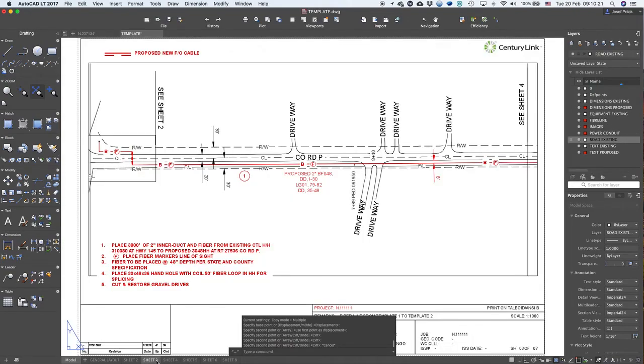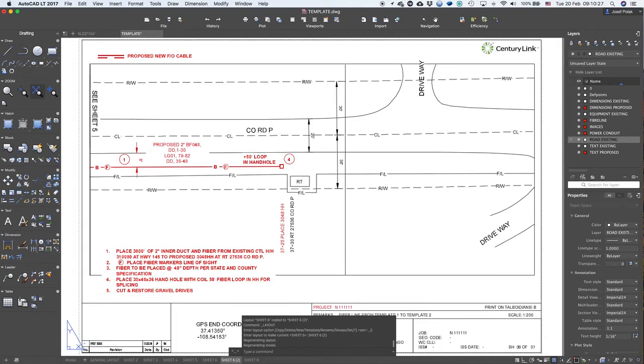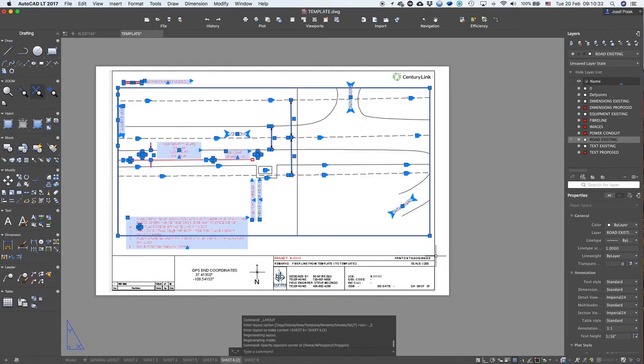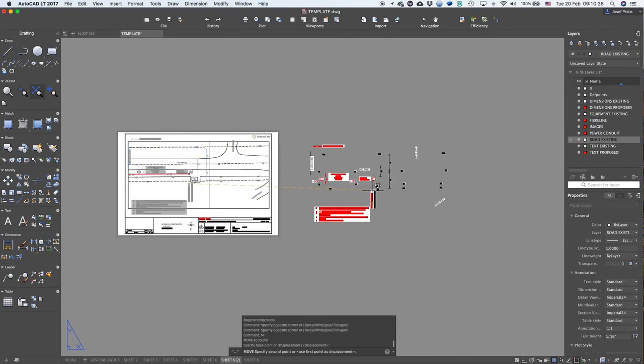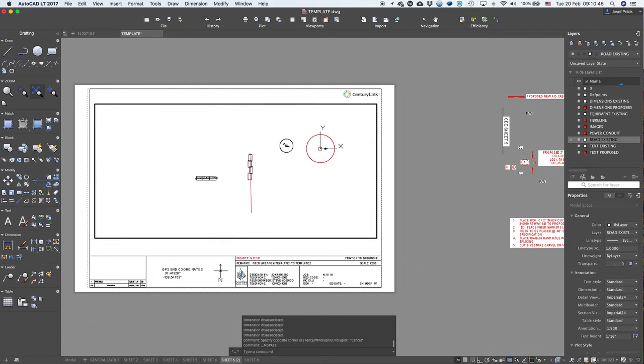So I just create a new sheet. Yeah, so I create a new sheet. I just move all the labels, keep only the viewport, move it somewhere else so it doesn't disturb me, then I will edit. So if you go to the model space, you unlock the model space, you can zoom out, doesn't matter.